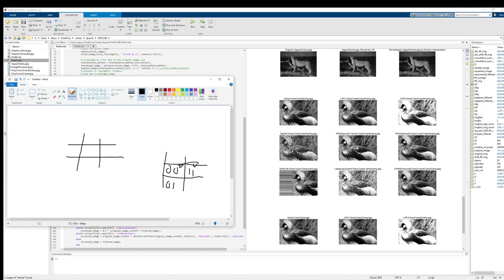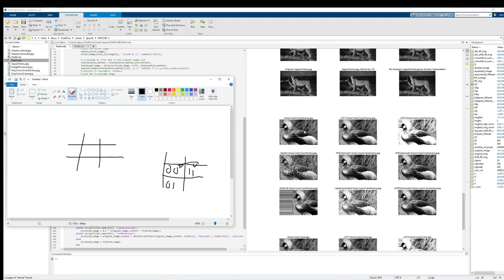So you could see, with this grainy image, that graininess is basically a bunch of high frequency points across the image. So when you pass a high pass filter through that, like you see here and here, it's going to almost make it worse in a sense because it's just highlighting all that grainy effect, which makes it look worse from a human's point of view. And the low pass will help the grainy effect from a human's point of view because it'll smooth out those large differences.